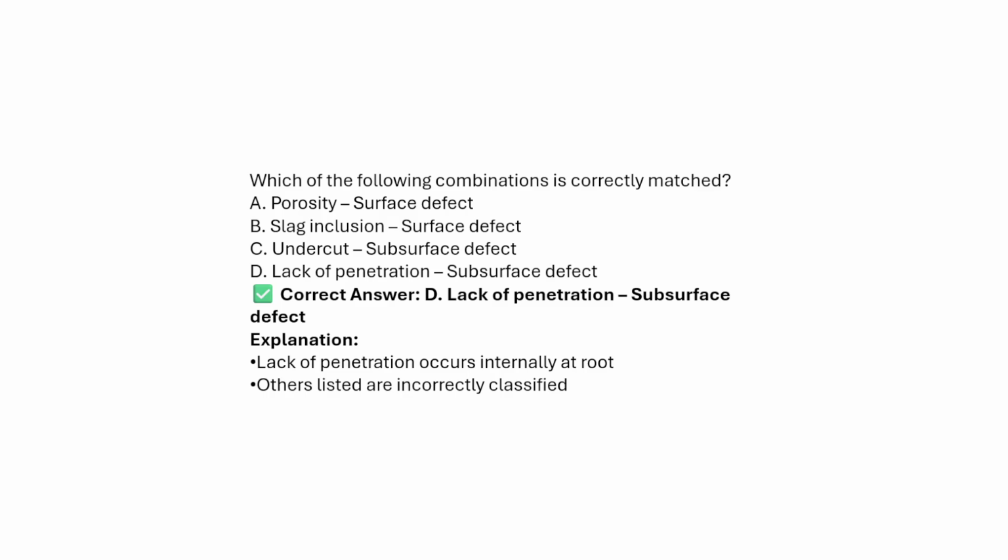And undercut, subsurface defect? No, undercut we can see on the surface, so it is not a subsurface defect. Lack of penetration is a subsurface defect. Yes, because lack of penetration is inside the weld bead, so it will be a subsurface defect. Lack of penetration occurs internally at the root. The others listed are incorrect classifications.